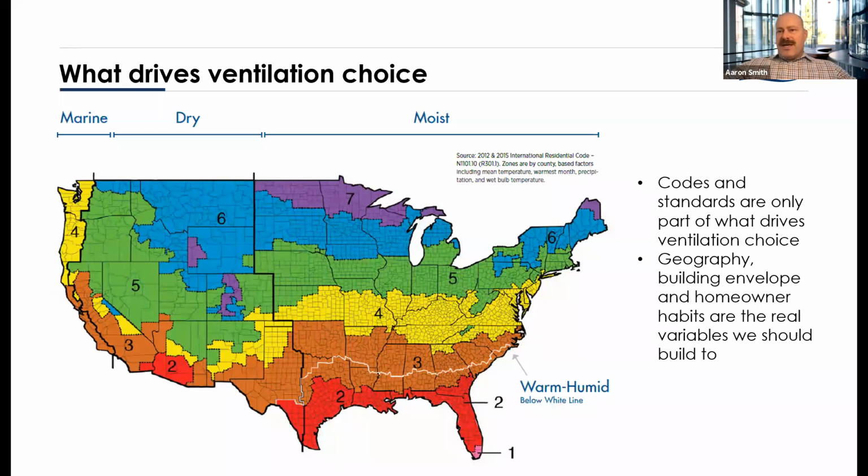I would put ductwork in with returns, so I was ventilating at least the bedroom areas, maybe a main living area. I try to pull as much air through that system as possible and dehumidify that air.